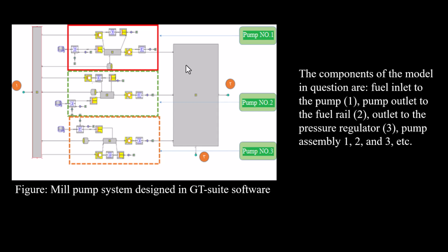The structure of the model in GT Power consists of a piston, a spring, and a mass. The piston represents the reciprocating mechanism of the pump. In GT Power, it is modeled using a part such as a reciprocating mass or a user-defined piston.